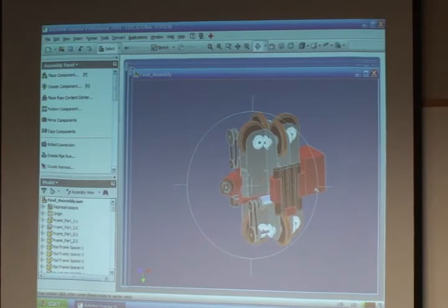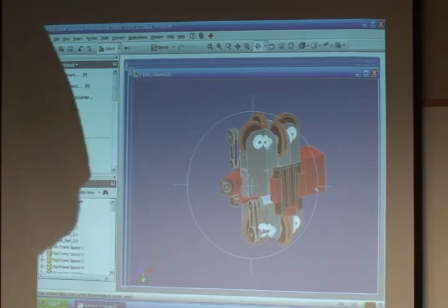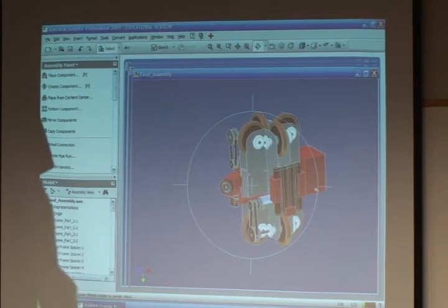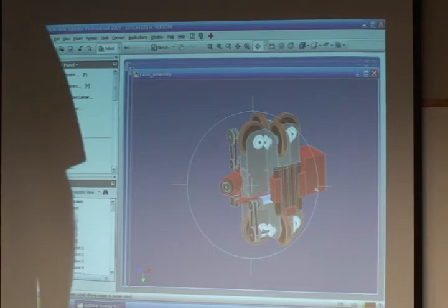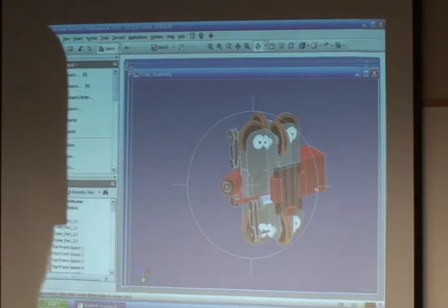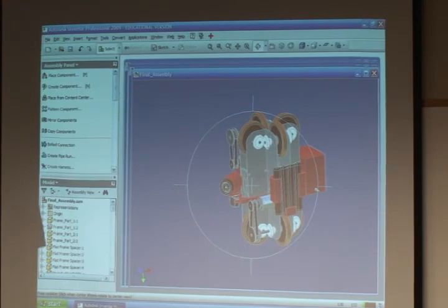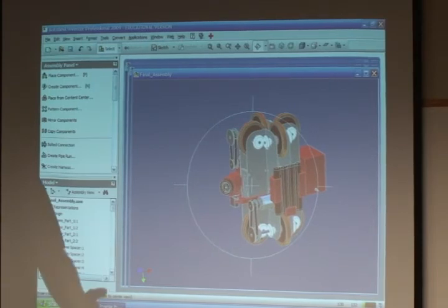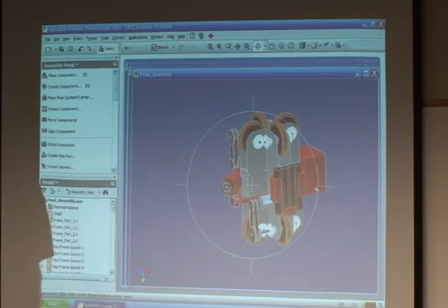A lot of times what we'll do is use Inventor, and then for the test weight or something like that, we'll bring it into SolidWorks. Import it in. An IGES file is good to import with, and so is STEP. STEP is open source. I'm pretty sure the machine companies, the NC equipment, want an IGES file. So you want to check with whoever's going to do your machining what file they want, so that they don't have to be converting.